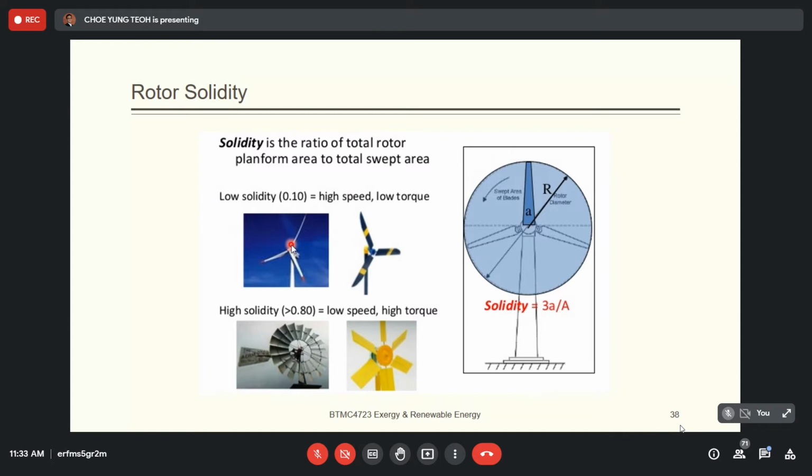So that is why we need the gearbox. But with the gearbox, another problem is the gear ratio. We try to minimize the gear ratio so that it will be cheaper and need less maintenance. To minimize the gear ratio, it means you need to use a high speed system, with a high input so that you don't need to amplify so much to generate electricity. In general, going from 60 RPM to maybe 1000 RPM is quite a lot already.